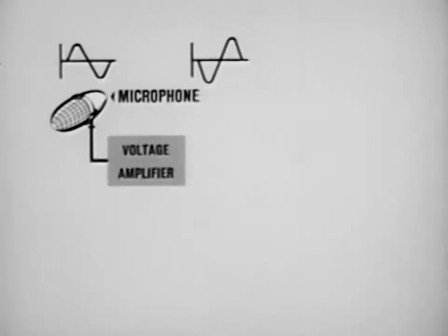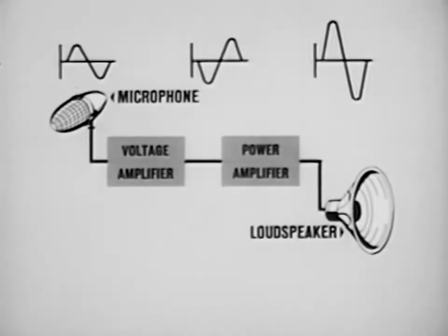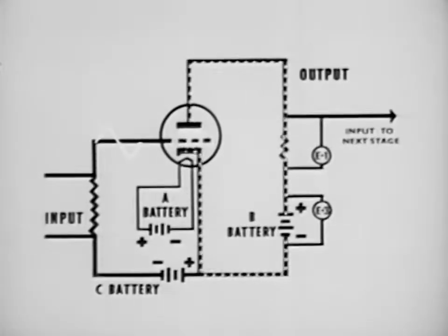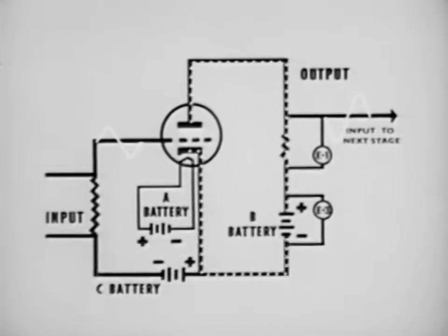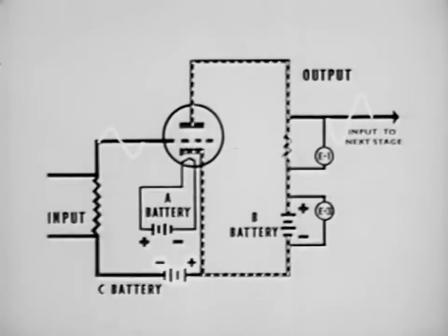This amplified voltage is applied either to another stage of amplification, a loudspeaker, or some other device which uses the amplified output. It should be especially noted that the original signal influences only the current flow through the tube. And the plate voltage change becomes a new signal, which is an amplified reproduction of the input signal. The amount of bias placed on the tube determines its operating point.